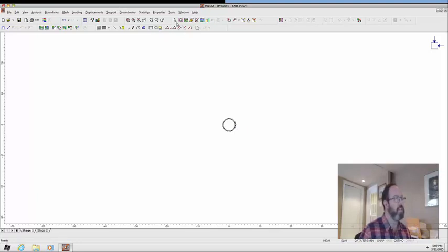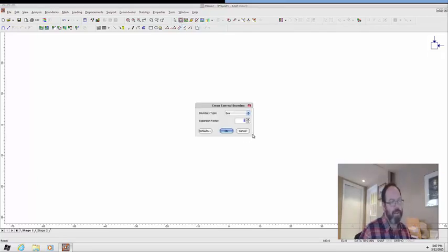Okay. So I'm going to go here and I'm going to add an external boundary, and it's going to give me the option of automatically selecting a box type boundary around my circular tunnel, and it's going to use an expansion factor, which is kind of a multiple of the radius, and I'm going to use, say, 7.